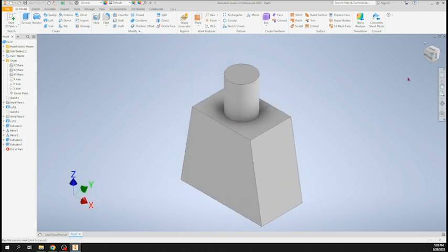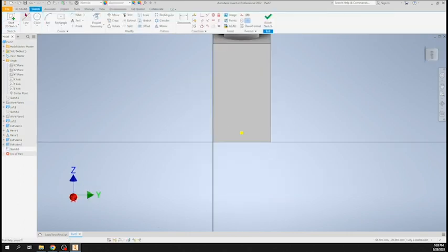All right, only a few things left. We got to do the armholes, so let's take care of that now. Go ahead and start a 2D sketch, and I want you to click on this surface right here. And then get your circle command out and move the cursor over to the bottom of this line until it finds the midpoint. Okay, and then slowly drag the mouse up, and what you'll see is a trailing dotted line. That'll help you keep it right in the center. And when you get roughly to 2/3 of the way up, go ahead and click, and we're going to type in 3.8. 3.8.